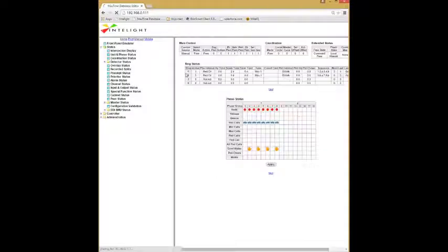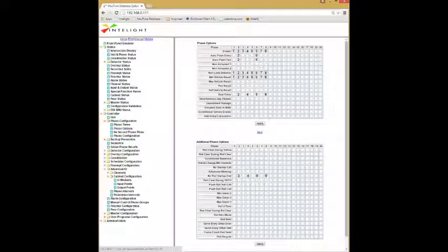So now we need to do a little setup, right? We're going to look at our unit phase status, make sure we're cycling, we're running phases, the countdown timers are running. Notice that I have recall set. I did that under phase options, so I wanted to make sure that we're cycling sequentially. So I have min recall applied to phases 1 through 8. And what I want to do is have demand and then override that demand with the phase groups.